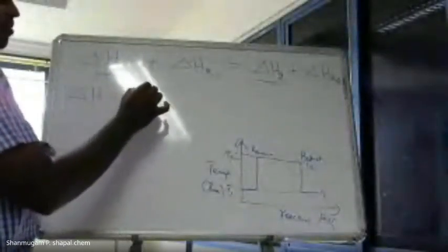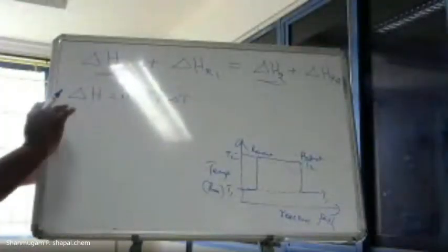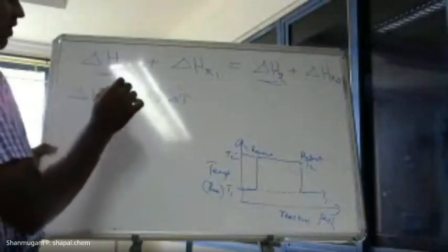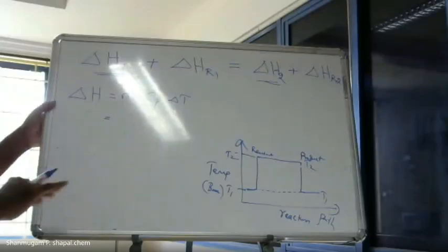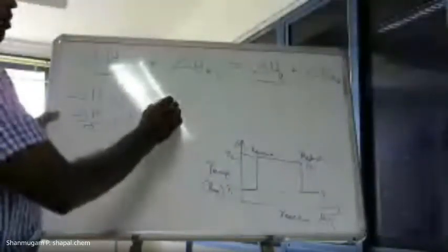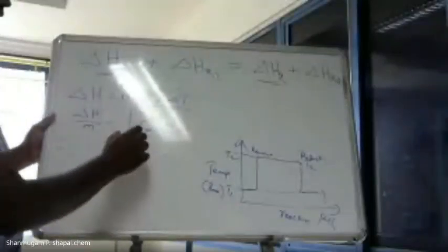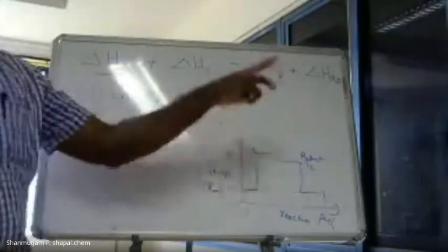So you will write mCp delta T in your heat transfer, right? Similarly here we agree that we will write mCp delta T, but you take it at the different temperatures, T1 to T2 Cp dT, because this one is not a gradient, it is an integral increase because of the change in temperature in the reactor, and again it will drop.